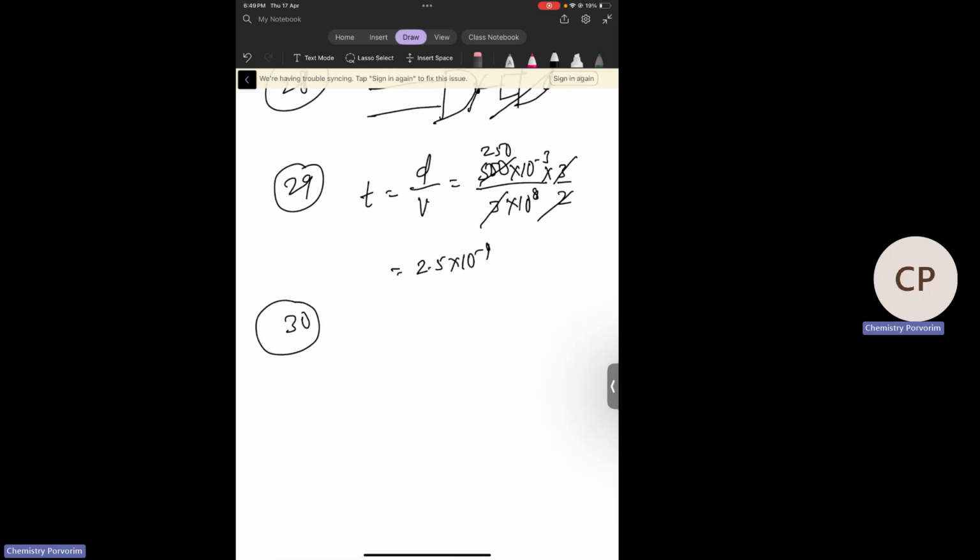Which voltmeter will give non-zero reading at resonance? At resonance VL and VC are equal and opposite, so V3 can be 0. Non-zero reading: V1 and V2 are non-zero, V3 is 0. Option D.